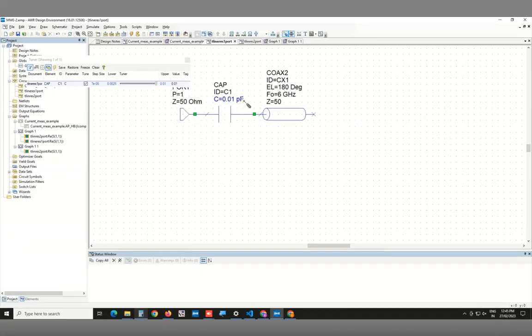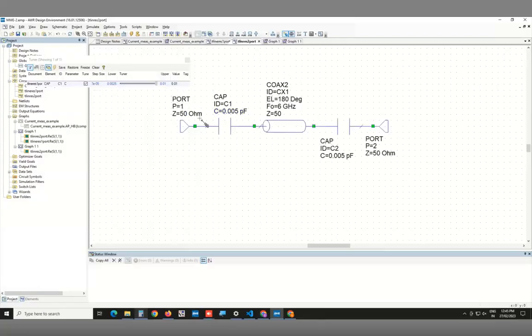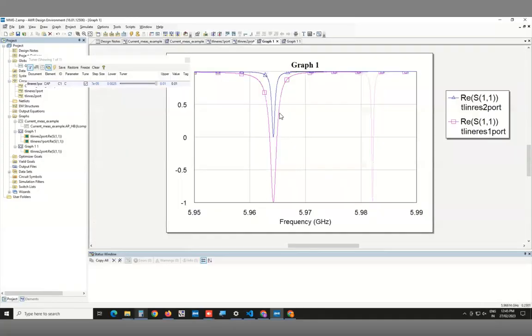But the Q factor, now the coupling of this 10 capacitors is actually higher, it goes as the square. Whereas in this case, because it's two independent ones, it just adds, the loss of this guy plus this guy just add together. So because of that, when you shift the frequency, the line widths don't match, which means the Q doesn't match. I mean, the problem looks much worse here because the curve only goes from 1 to 0, so it artificially looks narrower. Whereas this one, if I had stretched this out, it would have been a little broader.